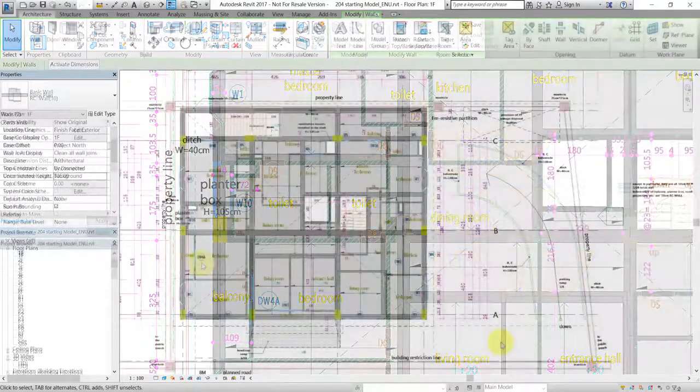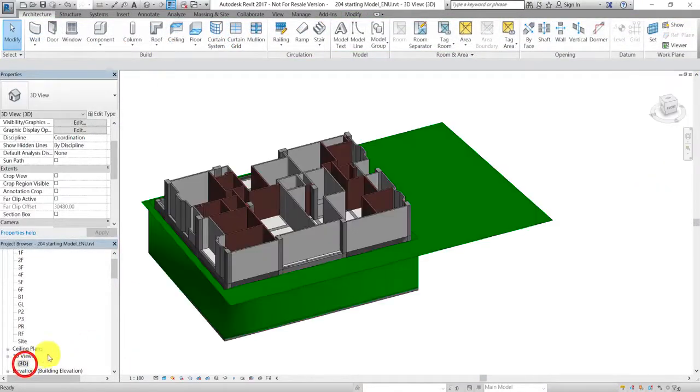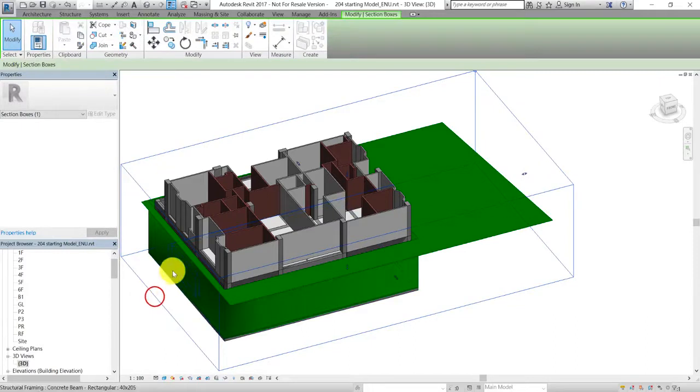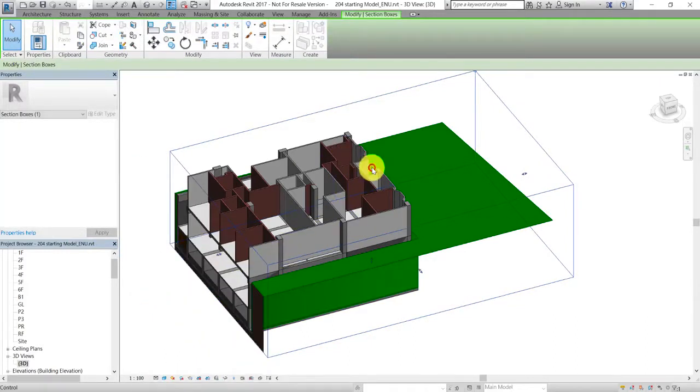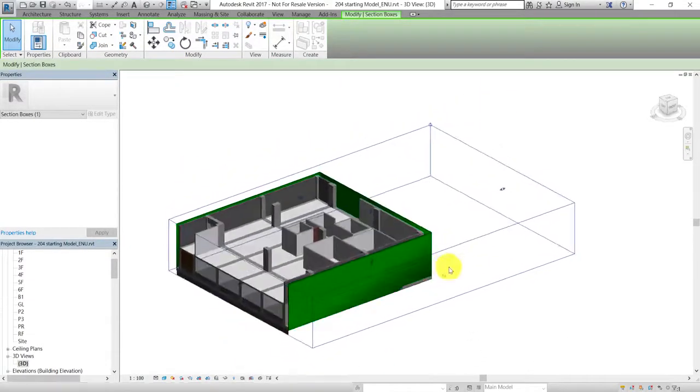After the wall construction is done, we can go to the 3D view to browse the results. In the Properties palette, check Section Box and adjust the boundaries of the section box. We can now see the complete structural columns and RC walls in B1F.